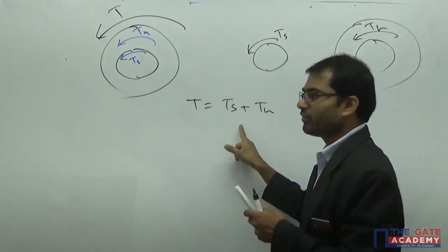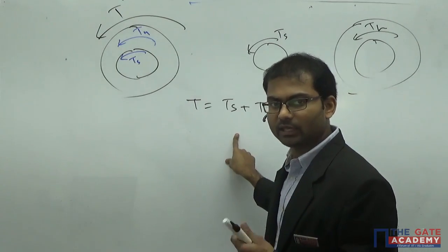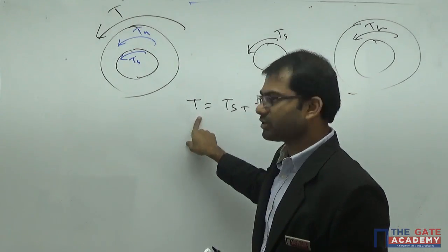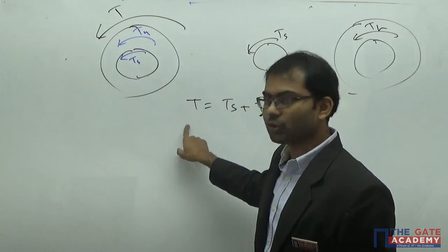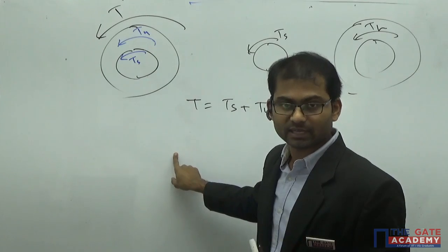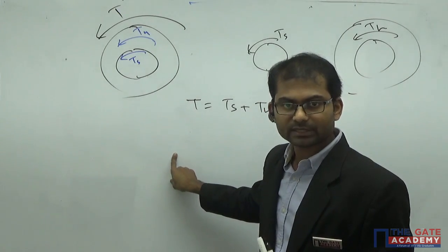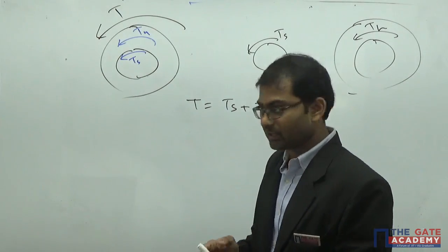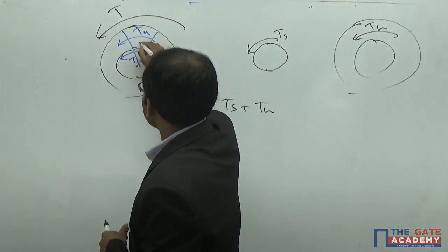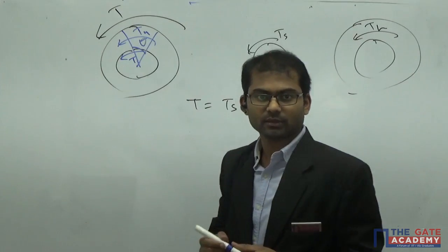So this is only one equation which you are getting from equilibrium. Understand? One equation but two unknowns. So this is also a statically indeterminate case. So we need a compatibility equation. The compatibility equation which you will observe here is the same thing as the earlier case. The angle of twist is same in both the cases.